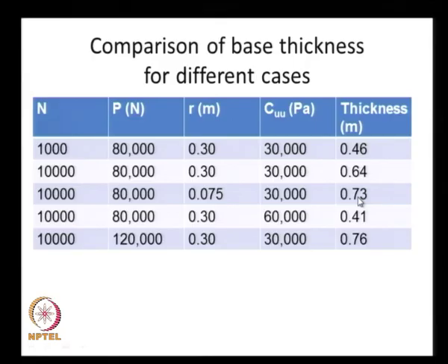So that means that if we have a lower tolerable rut depth, we need to provide a thicker granular base, so that our combined stiffness is higher, which results in less rutting. And the influence of Cu: the increase of Cu to 60,000 pascals is to reduce the thickness.